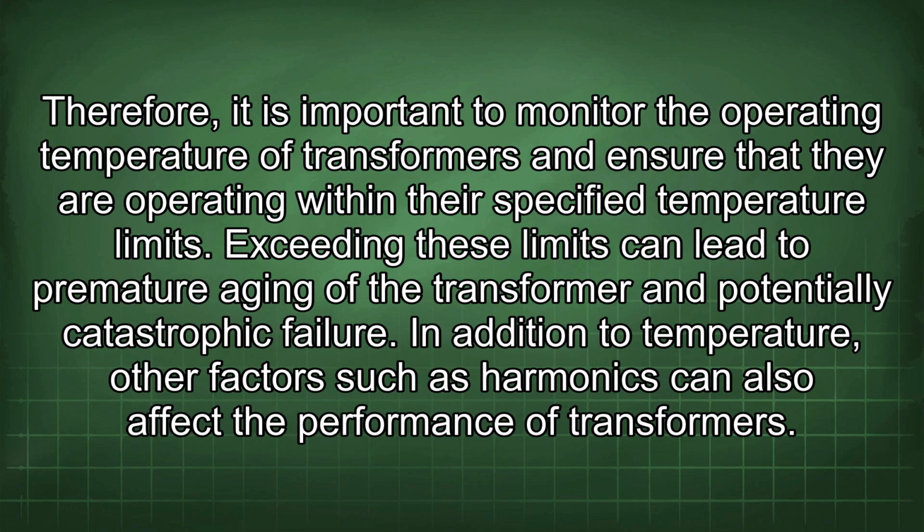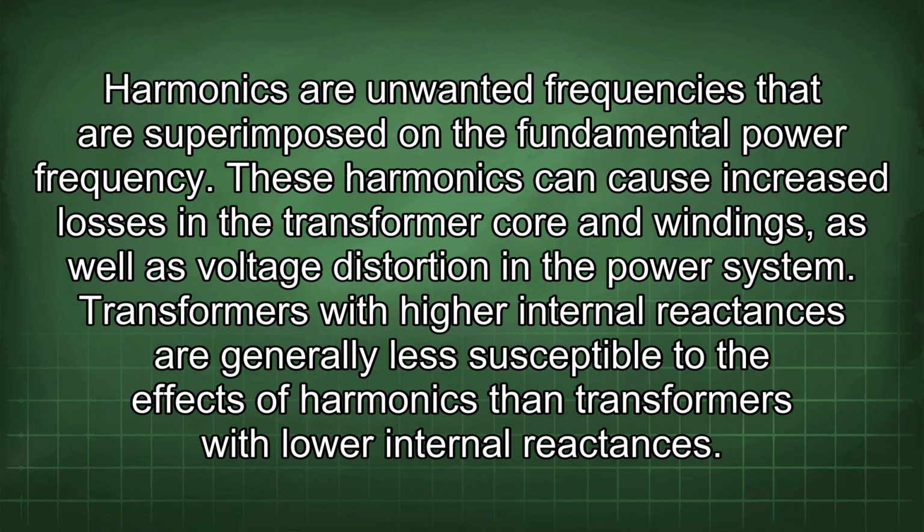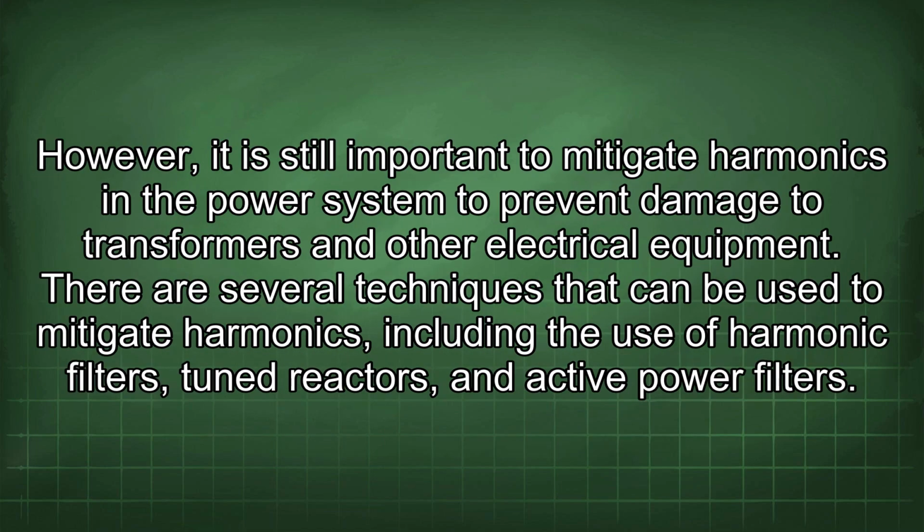In addition to temperature, other factors such as harmonics can also affect the performance of transformers. Harmonics are unwanted frequencies that are superimposed on the fundamental power frequency. These harmonics can cause increased losses in the transformer core and windings, as well as voltage distortion in the power system. Transformers with higher internal reactances are generally less susceptible to the effects of harmonics than transformers with lower internal reactances.